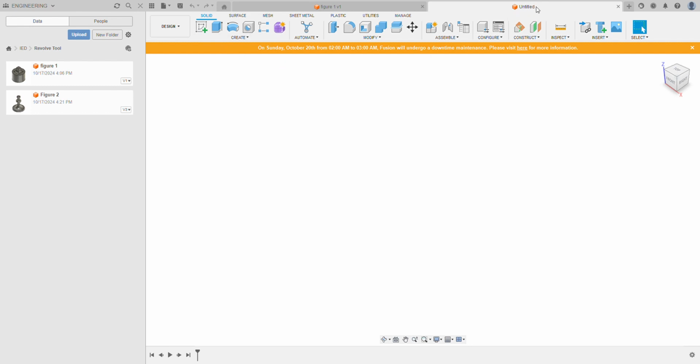So we made a new design, and before we even move forward into making a sketch, I'm going to open up document settings. It says inches, because that's what our default is. I'm going to click on this, and instead of inches, make it millimeters, just because all the numbers in our sketch are very large, and I feel like it's much more likely that it's intended to be millimeters.